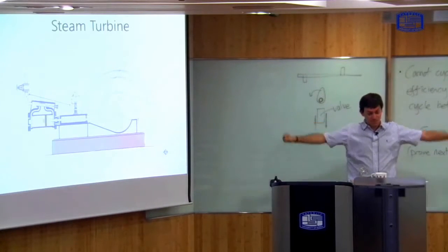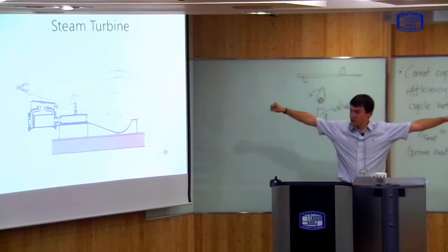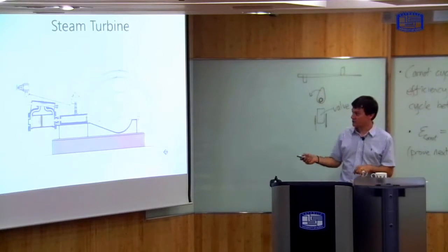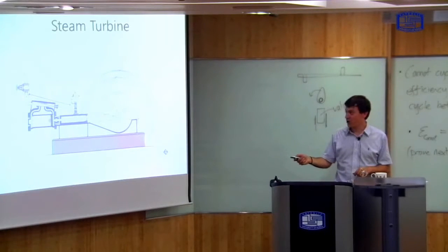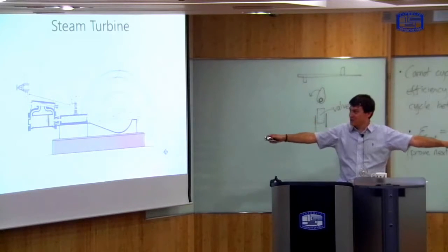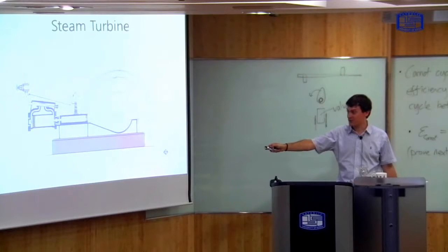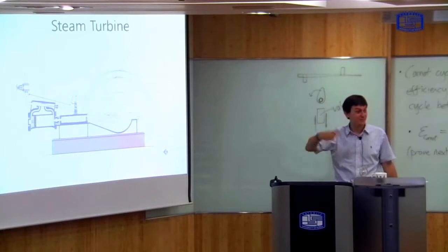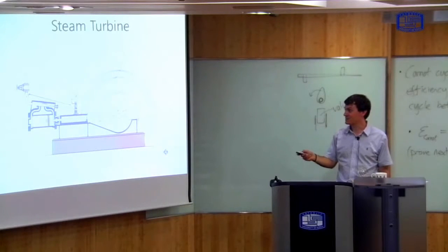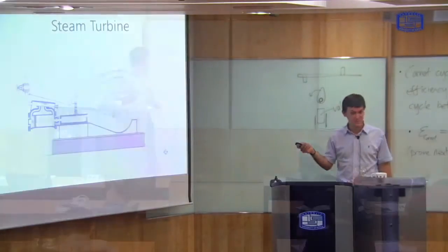Now, the faster you spin, the higher and higher these balls will go, because the centrifugal force is getting stronger and stronger. And at some critical point, if the balls go too high, which means that the wheel is going too fast, it will turn off the supply of gas to the turbine. So if the wheel goes too fast, then the balls will rise, and the motion of the balls going up will pull this lever, which turns off the gas going into the turbine, and this shuts down the system. Okay? So this is a mechanical mechanism through which you can stop the engine if it's going out of control, if it's going too fast.